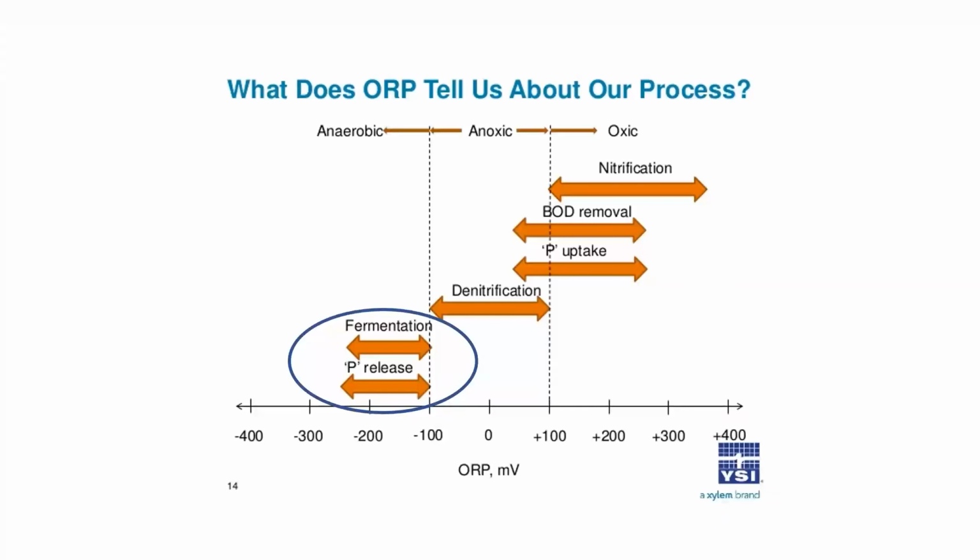For phosphorus removal, we're starting at the other end. We're starting way below any kind of detectable dissolved oxygen. If you have a DO meter, it's pegged out. Not at the top end, at the bottom end, it's at 0. And so we want septic conditions. I like to see that minus 200 right there. That's my initial target.